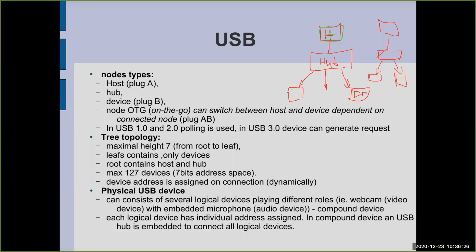If you connect it to the controller where the keyboard, camera, and other devices are connected, the performance will be lower than when you connect it to a controller where nothing else is connected. Because you should remember that this is a bus, so the throughput of this interface has to be shared among all devices which are connected.